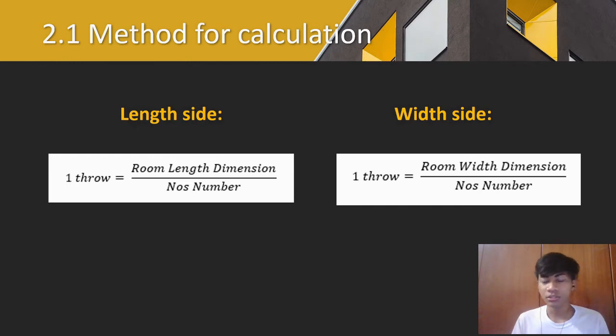The formula used is clearly related to the area of the room, because we were assigned to make an air conditioning system for the whole building. There must be many rooms in that building, and each room area is not the same. The way to calculate the throw radius for each room is to calculate the average length and width of the room, as the formula given.